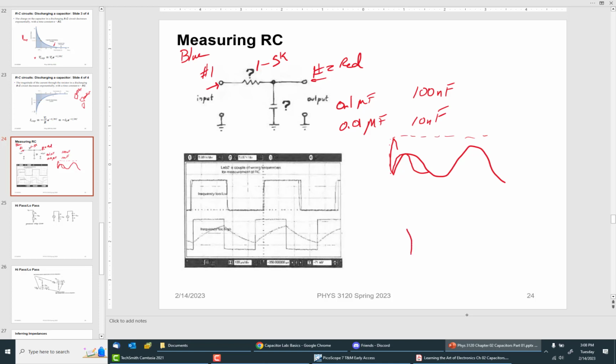As you get more and more sine waves, you have something that looks like this. And the more you add to it, the more you square out the corners. So the reverse of that is that when you pulse something with a square wave, you're hitting it with all frequencies. When we use a sine wave input, we're only hitting it with one frequency.